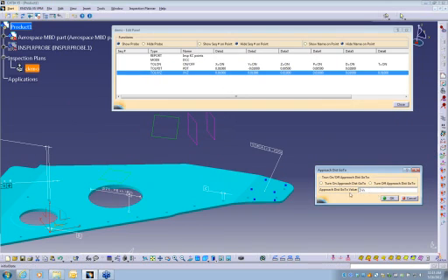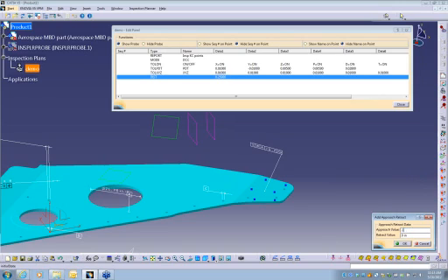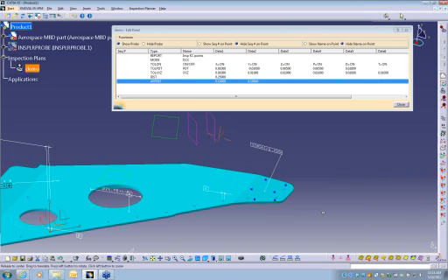We come in here, we can turn on the approach and retract. If you want to put approach and retract, for example, if you want to lift up before a hole or a point, a quarter inch, we'll put a quarter inch here. And we can also do the approach and retract of the machine. So let's just put 100,000 here. And you can turn the approach and retract go-to off too. You don't have to use that.